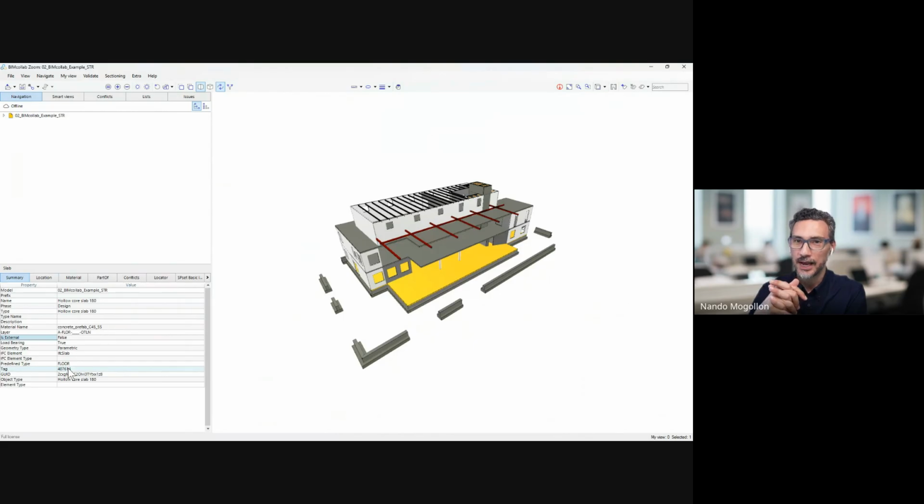That location of the site is usually what in ArchiCAD is called the survey point coordinates. So that's going to be one thing that we want to check. And then the other thing you want to check is the actual origin of the file. Because very likely, once you bring it into your own file, you want to be in a situation where the 000, or the origin of the three-dimensional file, matches regardless of the software that you're using.